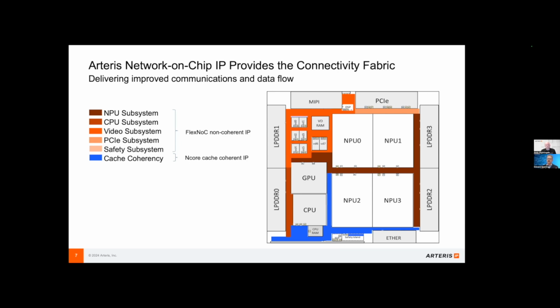And so when you're looking at a coherent system, you're looking at something like AI, for example, where you have lots of MAC operations operating in parallel, right? Yeah, absolutely. So you might have a number of different clusters, for example, CPU clusters that are working together. You might have 4 CPUs per cluster. They'll be perhaps working, if you talk about automotive, one will be working in a lockstep mode, one won't be working in a lockstep mode, but they still will be working on the same data or sharing the same cache information. These will be talking perhaps to other processing elements or offloading to a GPU.